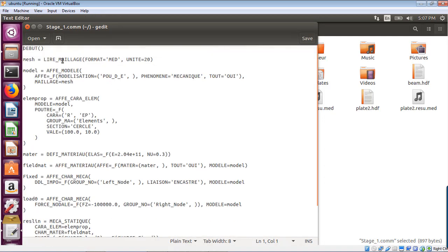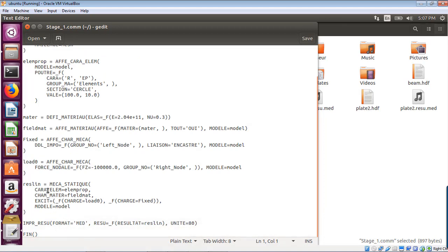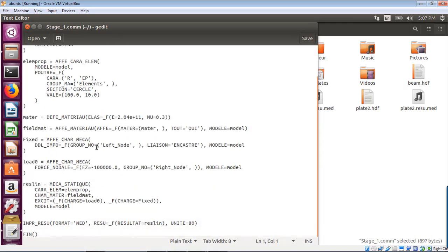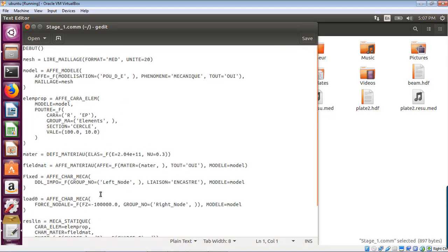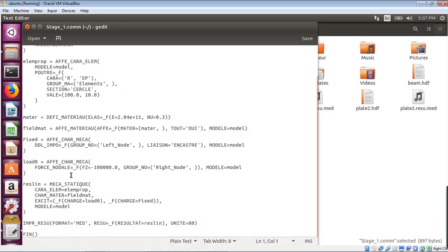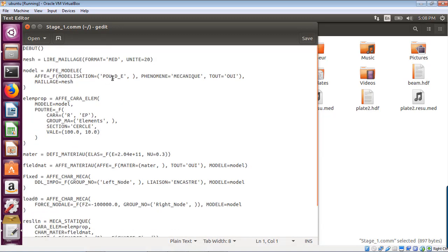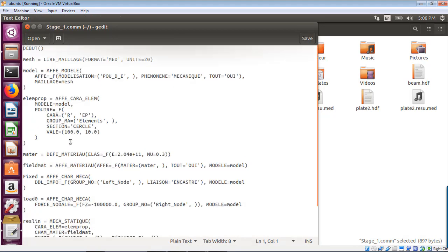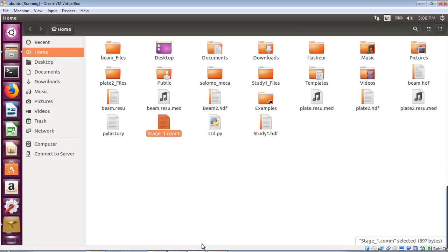So you see, this is basically everything I define in Aster study can be resumed in one text file. So you could just modify the text file with the right functions and run everything again, so you wouldn't have to go over all the steps in the graphical interface. For people who are really familiar with the name of the functions and what exactly they need, a small change here and they can run the analysis over and over, so that's pretty useful. But for those just starting like you, probably if you're watching this video, this is more complex.